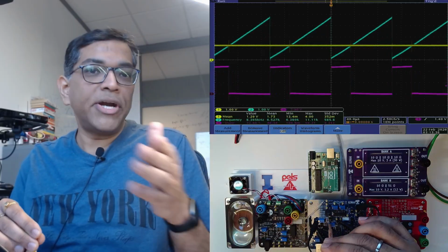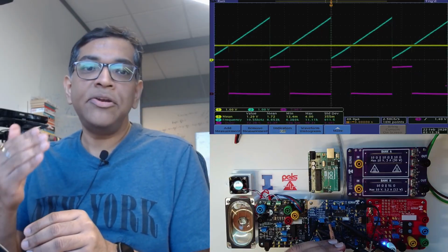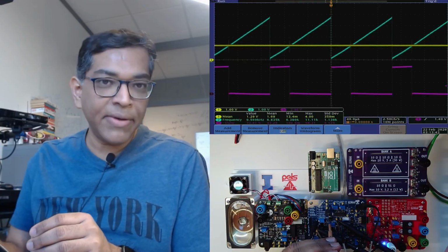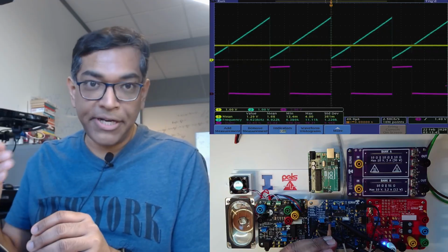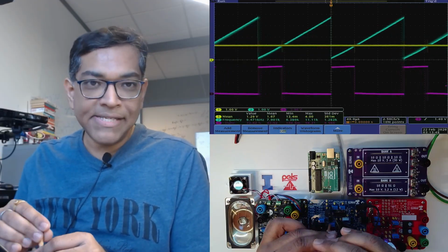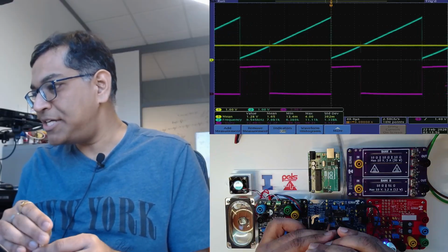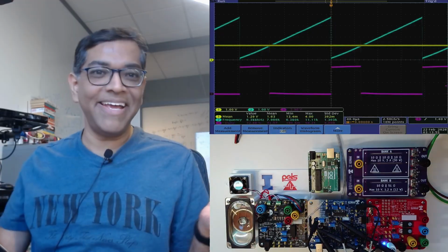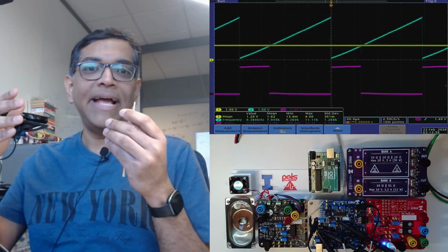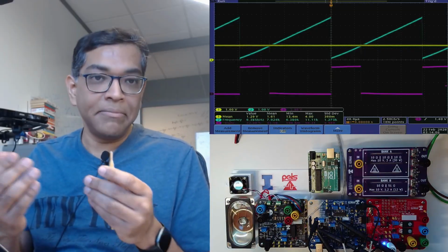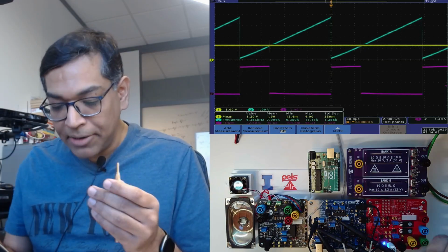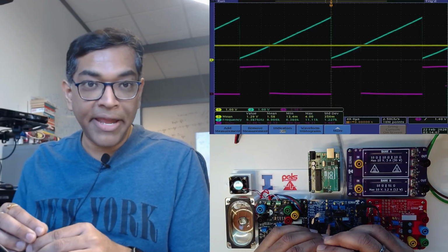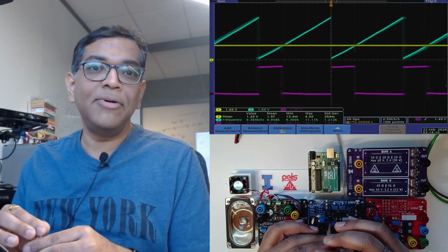Now what you will be doing in this lab particularly is to explore how linear this process is as you go through different frequencies and different ranges of duty ratio. At a very low frequency, the lowest we can achieve here is around 6 or 7 kilohertz, this looks pretty straightforward, pretty easy, right? I have a ramp, I'm comparing it, and I'm getting the PWM waveform. But things become more interesting and trickier as we start pushing the frequency higher.